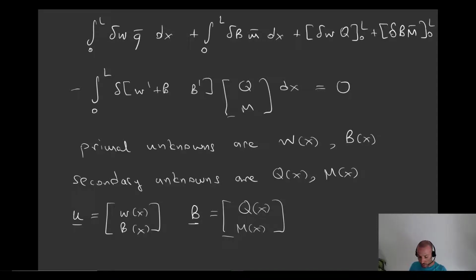As the next step now, I would like to look at this equation that we have above. This is just one equation that we've written, and this equation actually is to be solved for 4 unknowns, right? In this case, it's going to be, again, the vertical deflection, cross-sectional rotation, reaction transverse shear forces, and reaction bending moments. Now, I would like to say at this point that this equation is not enough for us. I mean, we have more unknowns than equations.